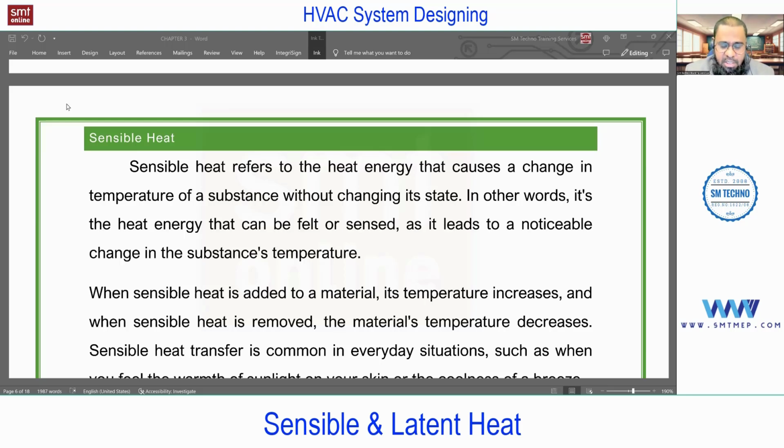I'll give you a few examples. We have a detailed list in chapter 7. At this level, just for example, heat gain through wall is one source. Heat gain through glass, nothing but window, or heat gain through partition, floor, ceiling, or ventilation and infiltration. Like this, you'll have people, lighting, appliances. We have a complete list. So remember, when we deal with heat gain through these different sources, first you must know whether the heat gain is only sensible or sensible plus latent.